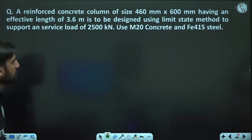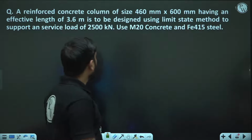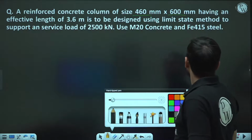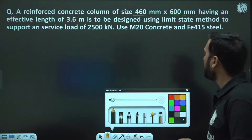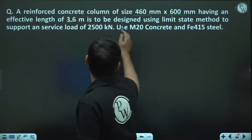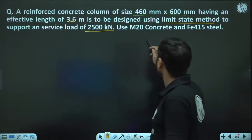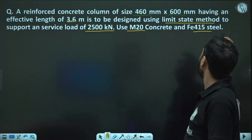What is given here is that an RCC column of size 460 by 600, having an effective length of 3.6 meter, is to be designed using LSM to support a load of 2500 kN. Use M20 concrete and Fe415 steel.